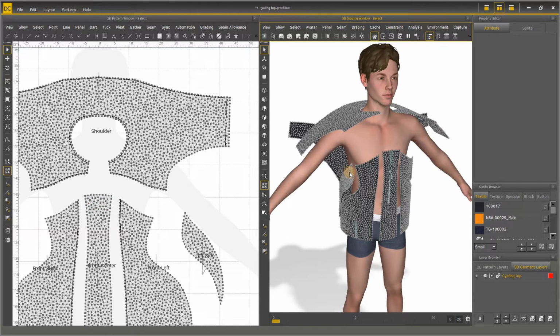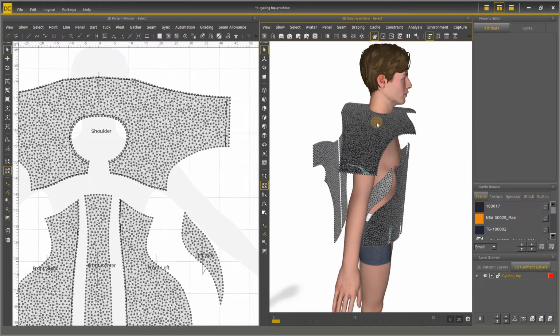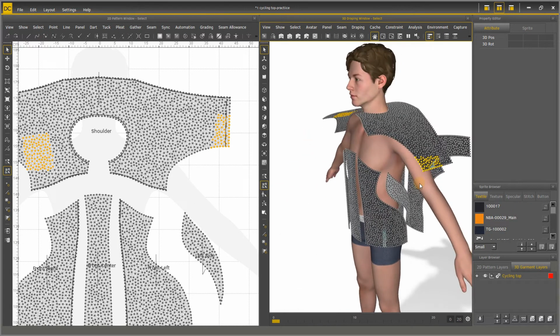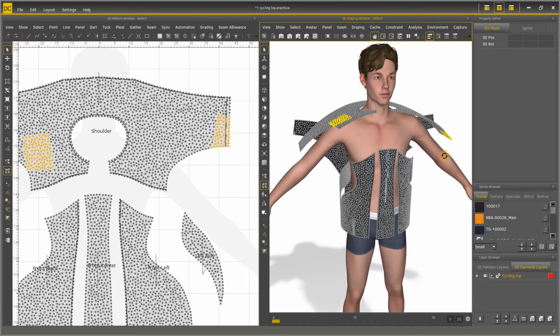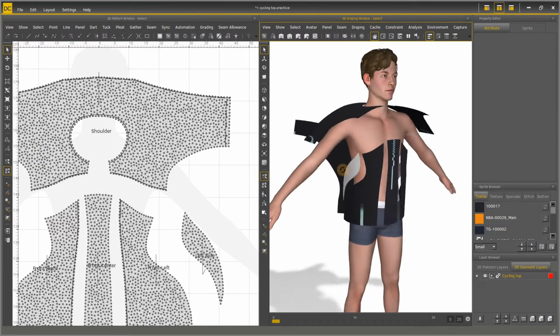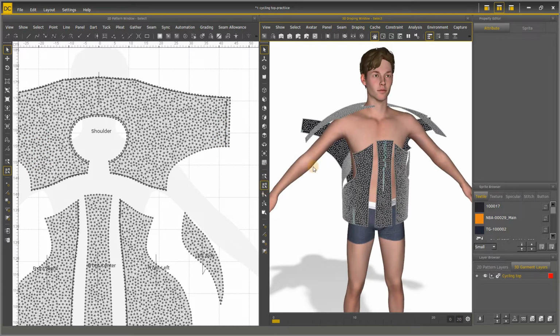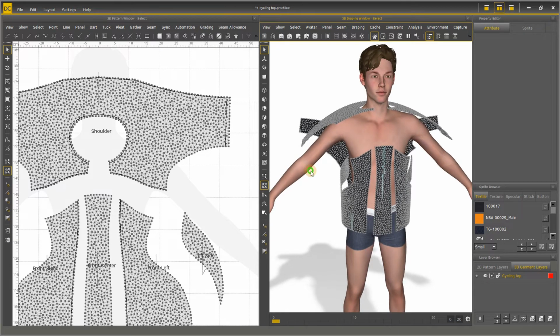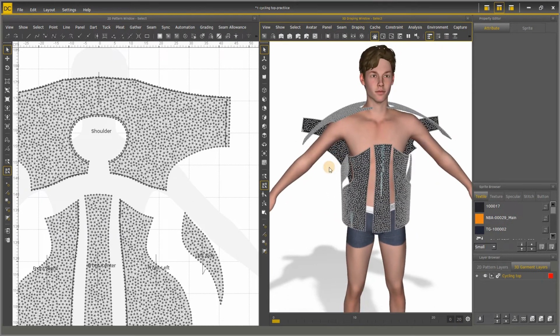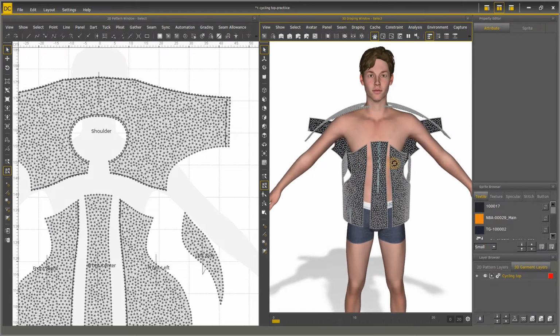For example, if I select the vertices from this angle, I cannot see the overlapped panels. I will accidentally select the vertices on the other side. Worth mentioning is that if no panel is selected in primitive selection mode and we just change to the vertex selection mode, all the panels will be in vertex mode, and it will be very easy to select the wrong vertices.